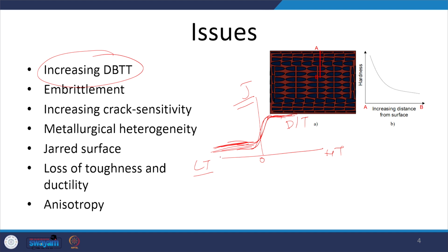So, we say that this kind of change in the toughness of the material with the drop in temperature is important. This particular narrow range of temperature over which such a sharp drop in toughness takes place is termed the ductile to brittle transition temperature. Obviously we will see here there is a range of temperature, and we can use the median if it is not very sharp.